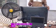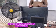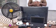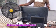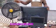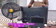Now, at times, the wattage may not be written there. What you see is voltage and amps. Power is voltage multiplied by current. So if you have the voltage, the AC voltage, and the AC current of this appliance, because these are all AC appliances, you multiply the current by the voltage.